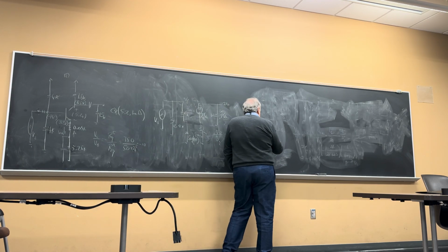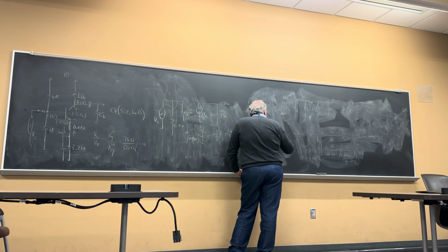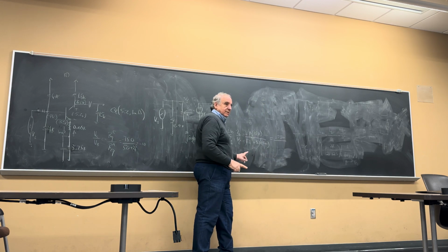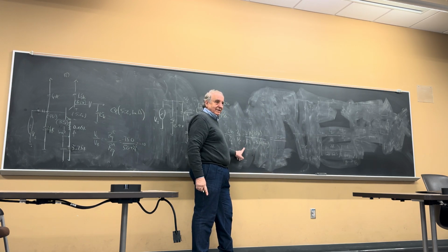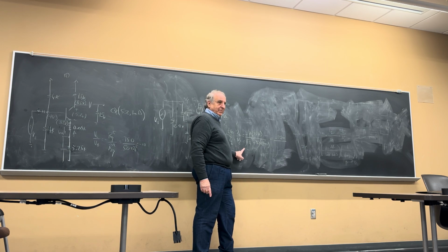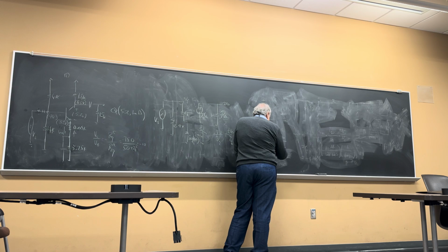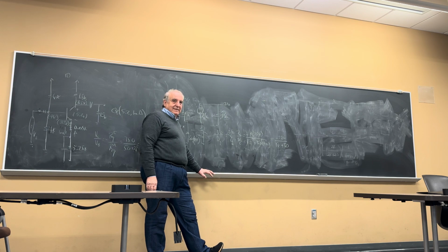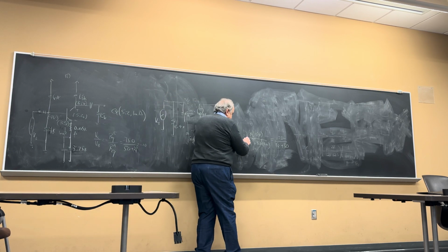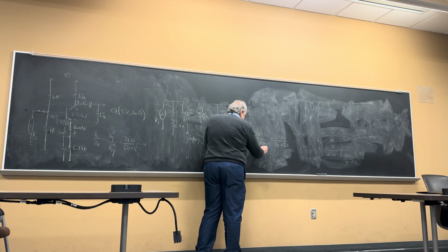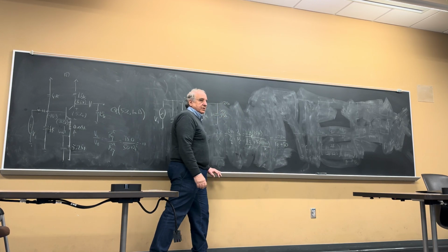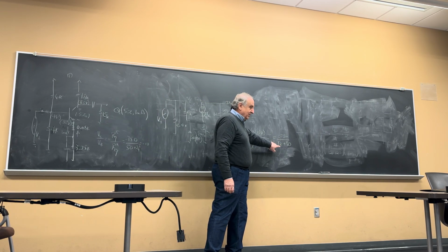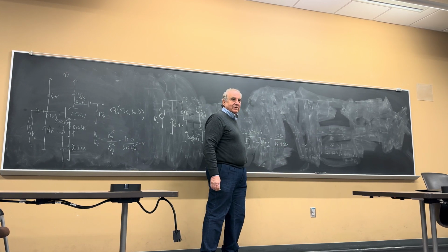Now watch this. Divide beta on top and bottom, you get minus 750. What's R pi over beta? R pi over beta, little RE. Because if you divide this by beta, here's the answer. R equivalent in the collector, divided by what is in the emitter, little RE plus the 50 ohm.